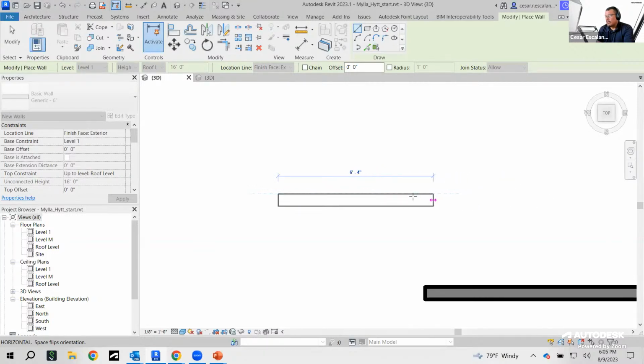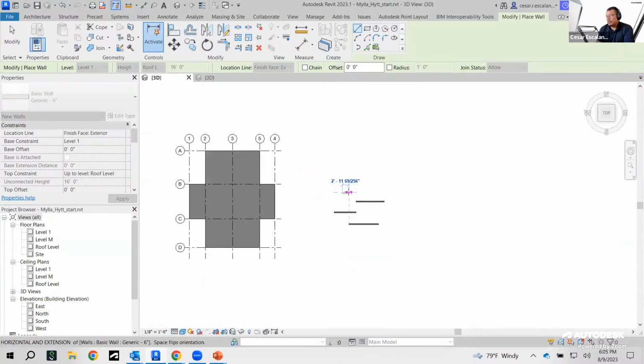You can notice that it snaps. In this particular example, it says snapping every inch. But the snap factor of the temporary dimension is a factor of the zoom. So notice this, if I zoom out a lot and I create a wall, notice now that my snap factor is every 6 inches.